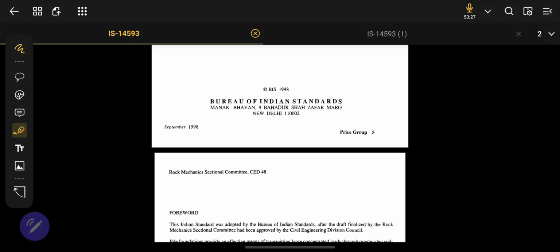So all these rocks are given in the categories of the rocks based on the qc properties, unconfined compressive strength properties, and SPT N values are given in IS 2911 Part 1 Section 2. There is a table by Cole and Stroud. This table gives the properties of the rocks, fractured rocks, and their classification. Based on that classification and field test values, N values, and lab test values, the qc values, we can classify the rocks, and based on that classification we can evaluate the pile structural capacity or the rock capacities for a given load.